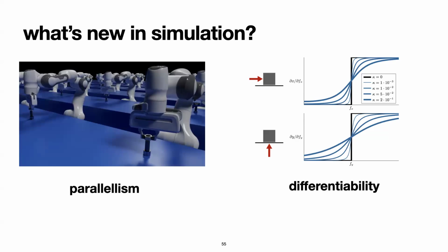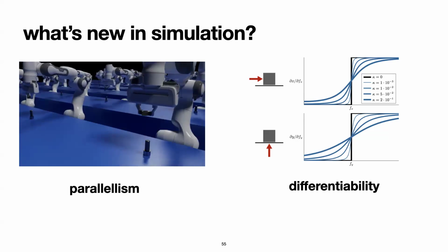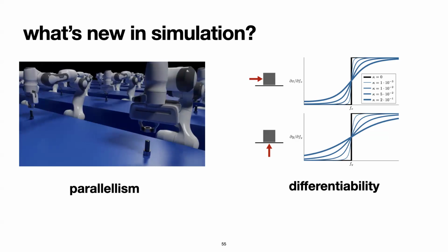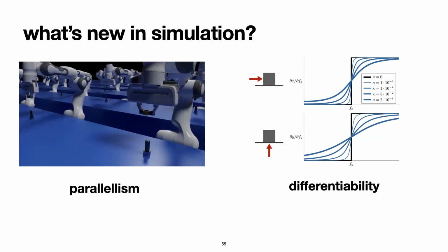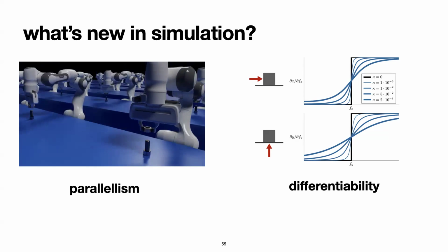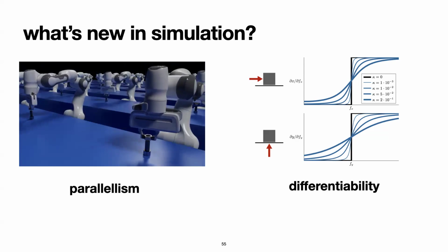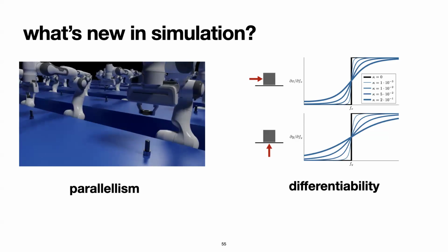Another thing that our lab has looked a little more closely at is how to actually differentiate through these simulations when we make and break contact in the environment. Contact is an inherently non-smooth behavior, and there's some way that we can compute these derivatives through this non-smooth behavior using some numerical smoothing, and then use these smooth derivatives to do model-based control.